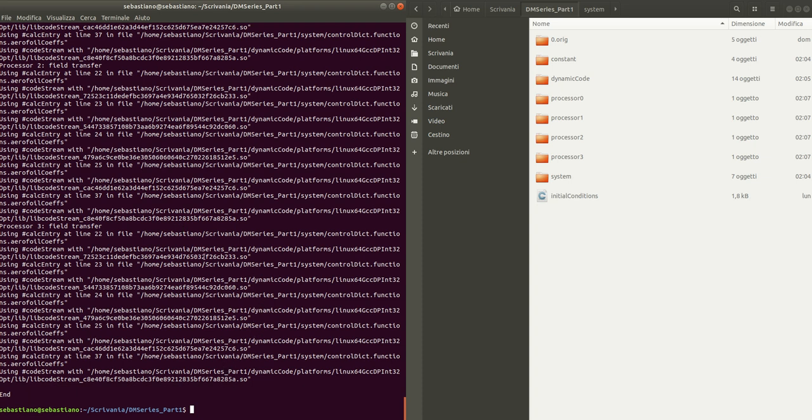Let's say that OpenFOAM doesn't have a very good scalability, because it happened to me to try OpenFOAM with very many cores, up to 700, and the scaling efficiency was not very good. But with laptops, with personal computers, let's say that it is good.